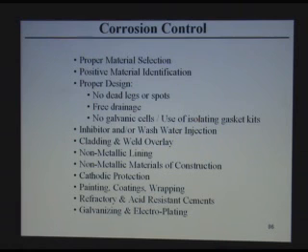We can use inhibitors where it is applicable. We can use water injection, as I mentioned, above the reactor effluent cooler. Inhibitors also are a barrier for corrosion, a barrier between the service environment and the metal. We use cladding, which is a high alloy steel on top of carbon steel, or weld overlay, that also is a high stainless steel type material, and this is again a solid barrier between the low material like carbon steel and the environment.